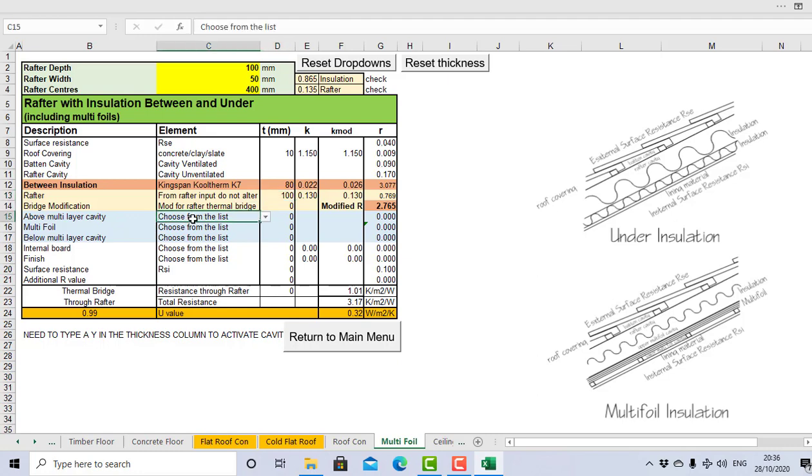Now, the low E cavities that I've given this is what I've got out of the BRE digests. The low E cavities that the likes of the multifoil manufacturers are taking into account are much higher. They go as high as 0.5. But I'm making this work with the real ones. And as far as the multifoils are concerned, I'm using the core R values, not these inflated full R values. It takes into account the cavities, because this program takes into account the cavities.